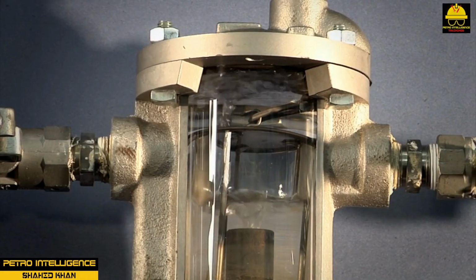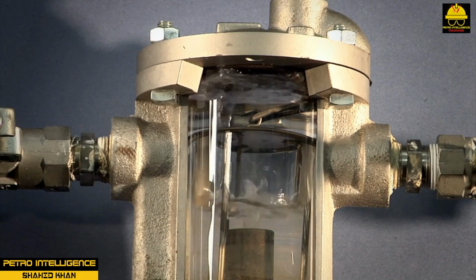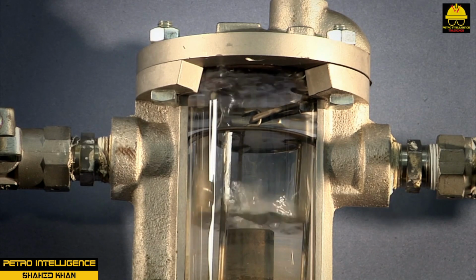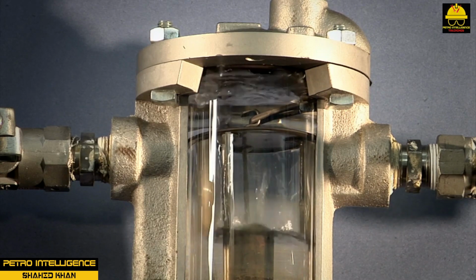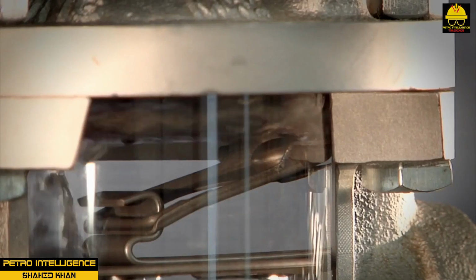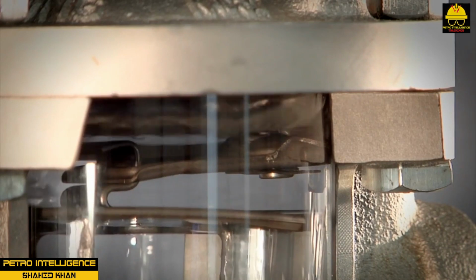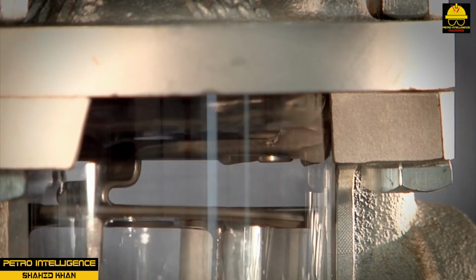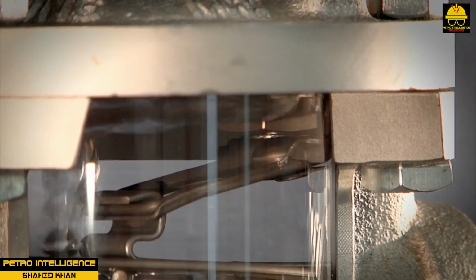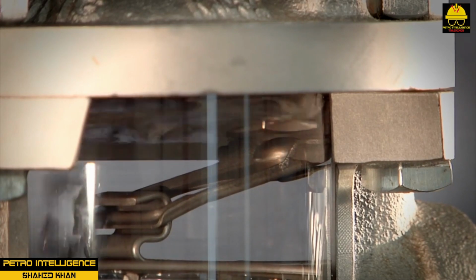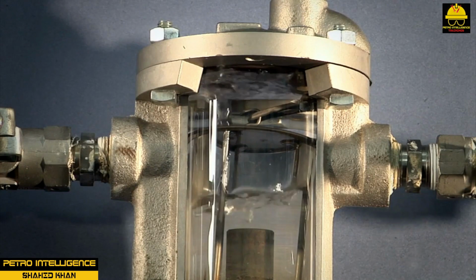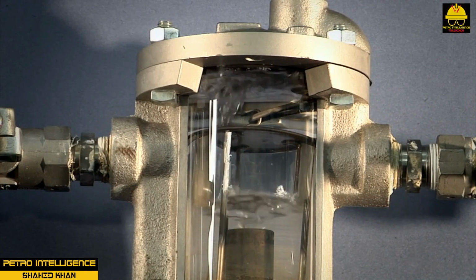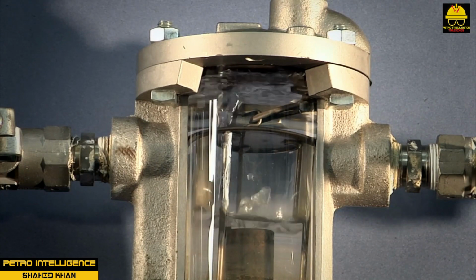Bucket steam traps are used on drip legs and tracing, with moderate heat loads. Operating pressure differential should be specified. Traps must be primed to function and will pass live steam when dry. Bucket steam traps will fail to open. They should not be used in intermittent service or used where steam is superheated. They can be used in continuous winter service, but the trap must be protected from freezing.